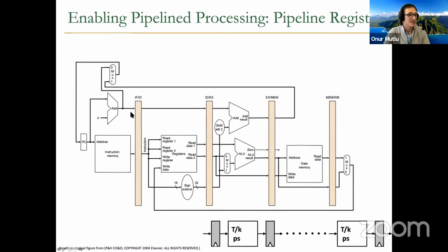So this is the pipeline register between, this is the instruction fetch stage. This is the instruction decode stage. This is the execute and address calculation stage. And this is the memory access stage. And this is the write back stage. And the pipeline registers are named based on the stages that they're getting inputs from and that they're driving.